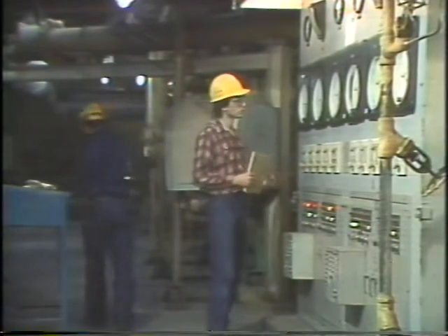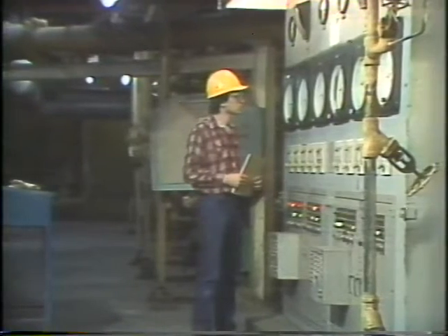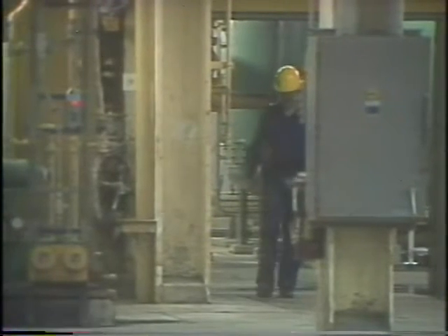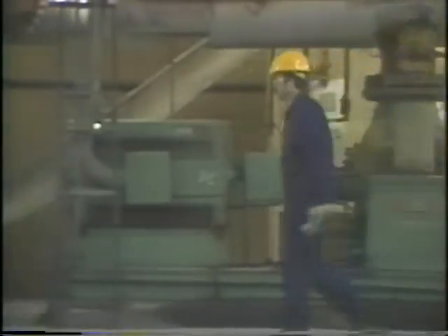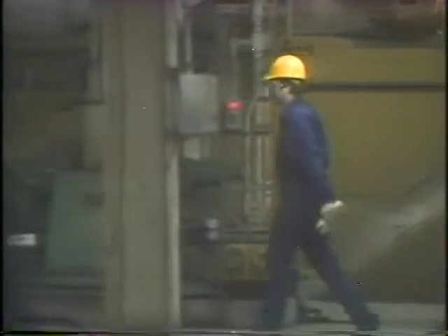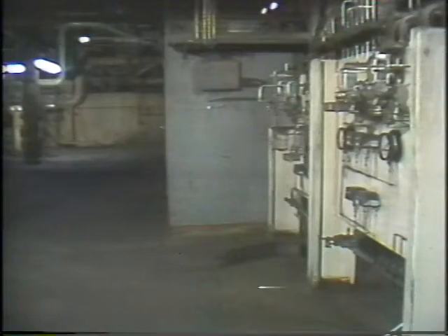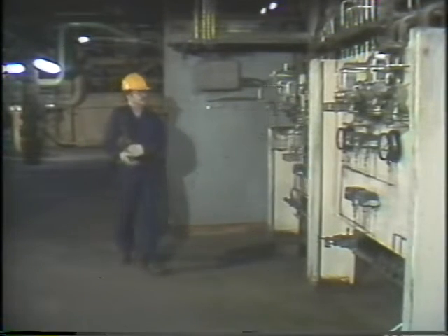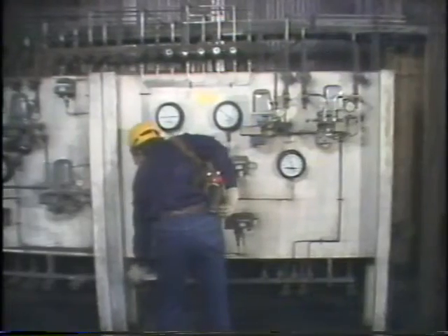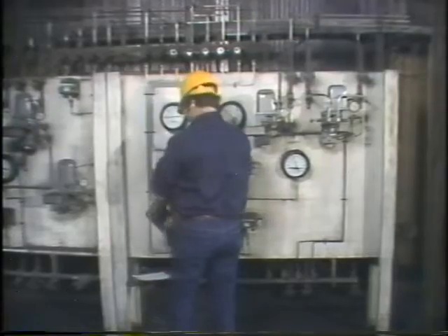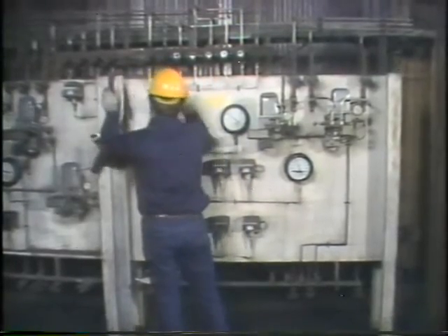Now, with the system in manual, I can make a few tests on the transmitter. That's about all I could find out from the operator. Since the steam flow looks like it's okay, but the drum level's off, which the recorder also shows, then it's probably the feed water transmitter that's causing the problem. I better not jump to any conclusions. I'll just look to see what I can find. I remember when I worked on this system the last time that the transmitter's on this panel. I'll put my tools up here, get them out of the way for a minute.